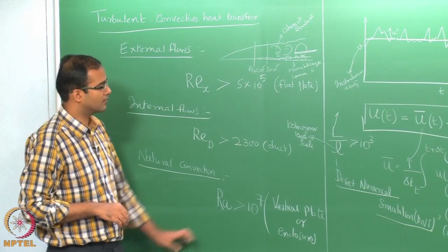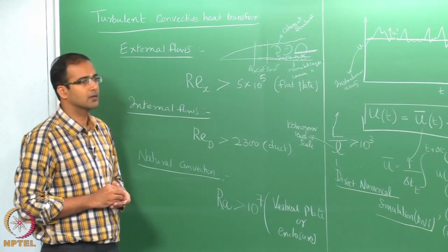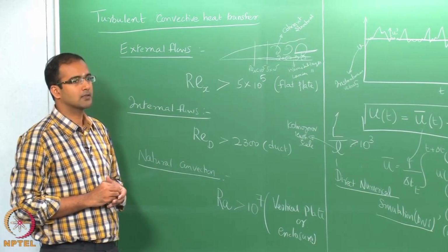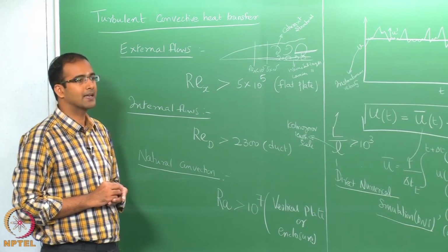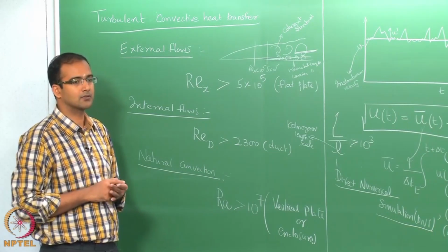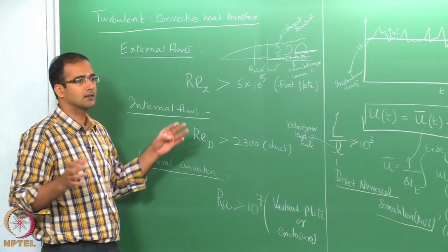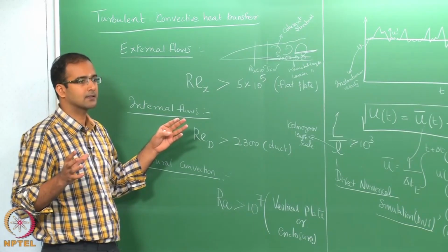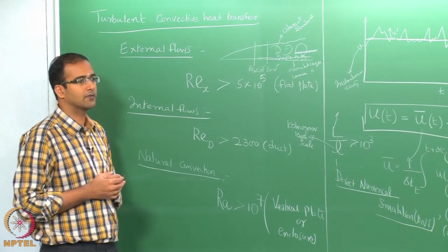So, this is called the Kolmogorov length scale, and if you plot what is called the energy spectrum, usually when you are doing a DNS, the first thing you are asked to show is the energy spectrum. It tells you how many turbulent length scales, turbulent energy scales, you have resolved with your grid.